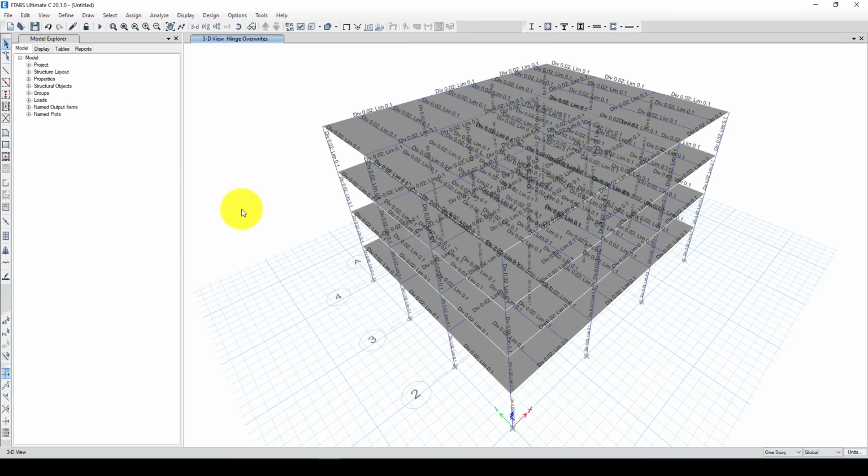So now we want to define the lateral force. So we can give the lateral force like 2000 kilonewtons in one or these 4 frames, and then push until the structure deforms, or 10,000 kilonewtons like this. So that 10,000 kilonewtons force can be distributed over the entire nodes, or also we can add, instead of the load, some sort of displacement in one node and then see how the structure responds.